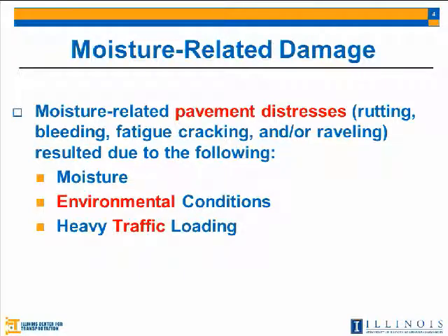Moisture alone is not sufficient to create moisture damage. We need another two important factors. We need heavy traffic loadings, and also we need environmental conditions. Fortunately, we have all of these factors working here in Illinois.